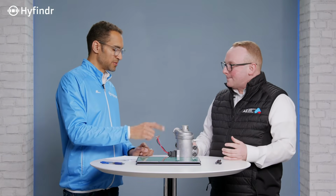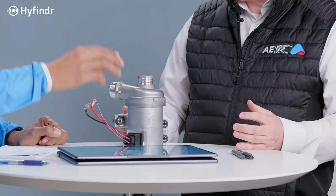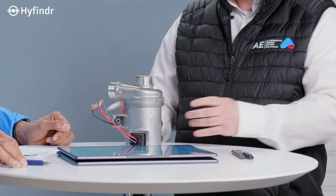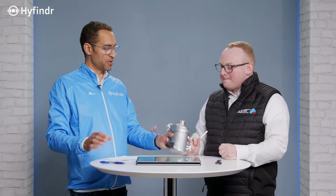So the coolant, ionized water, or what is it that you use? Exactly. The coolant pump is used for transporting the coolant medium through the stack, taking the heat out of the stack, and throwing it away with other components and so on. So the more you have to cool, the more this has to run. Exactly. And perhaps it must be bigger.